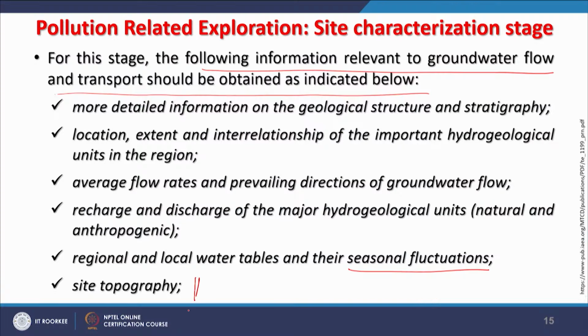For any new site, all these things are nowadays recorded in different reports, and periodically these are checked again. So, if the groundwater quality is deteriorating or the water is getting polluted, then stringent measures should be taken to protect our groundwater aquifers. And it is also very much required to know the site topography.